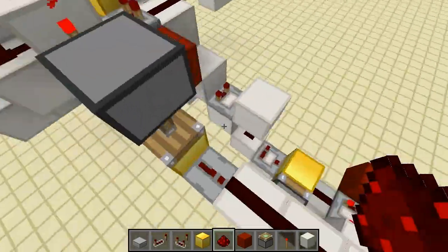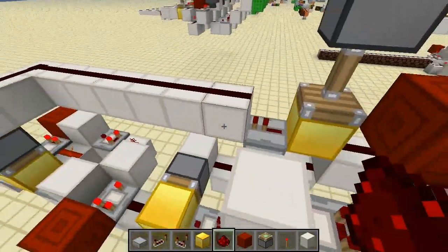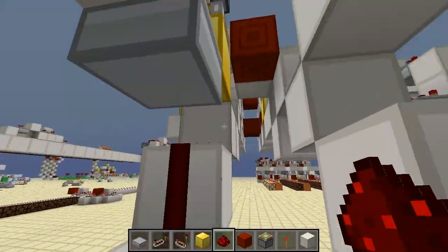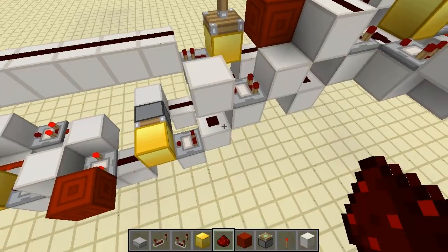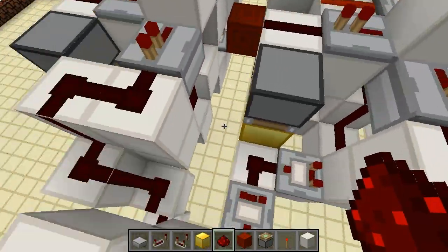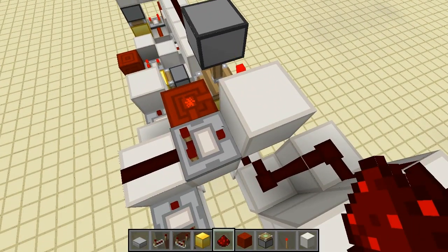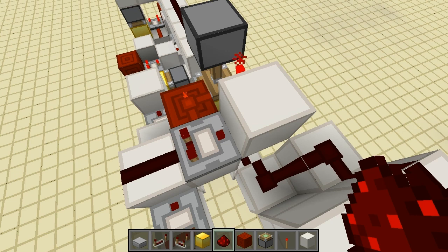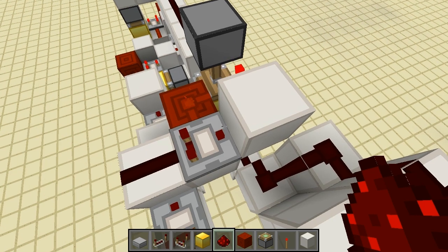Now the other thing we need to do is, if the previous carry is on and the input's 15, we need to set the carry out from this digit to 1. It'll already be 0 because it can't have an input of 15 and carry out from this digit, because that would mean that the sum of the two inputs, 15 and 15 at the maximum, was 31, which would be quite difficult.